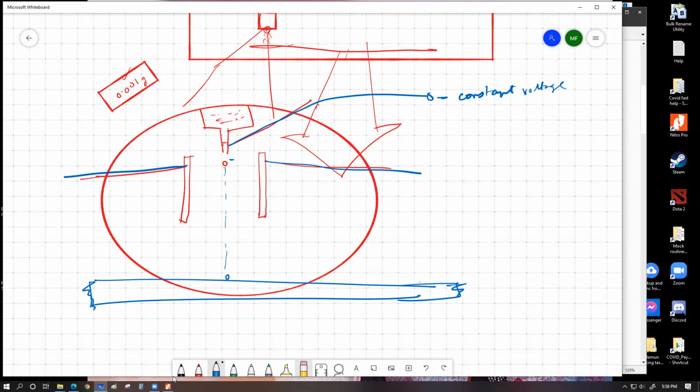Now, if we apply a little bit of positive charge over here and a little bit of negative charge over here, then you should understand that opposite charges attract and like charges repel. So this ink droplet is going to bend a little bit as it travels through the field, and it might drop somewhere over here. The gravity is pulling it down, but by applying this electric field, we are trying to move it in one direction. If we apply a much bigger voltage, then the bend would be even more, even stronger, so it can fall further away.